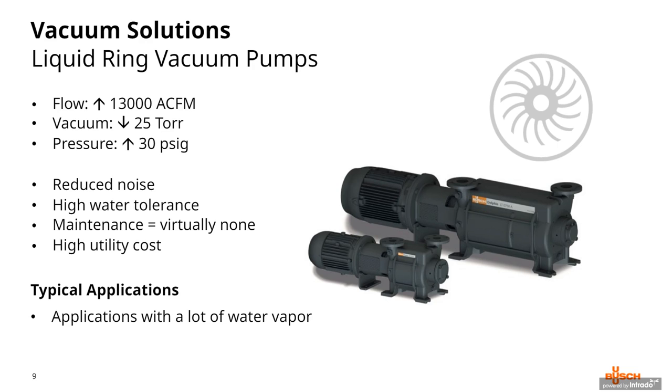This allows the liquid ring vacuum pump to be operated at relatively low temperatures. In addition, the temperature rise of the medium is kept to a minimum during the compression phase. For these pumps, packing as well as a variety of mechanical seals are available, including API 682.